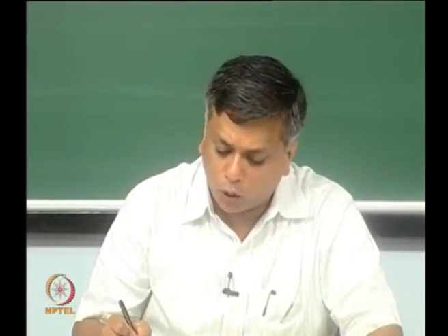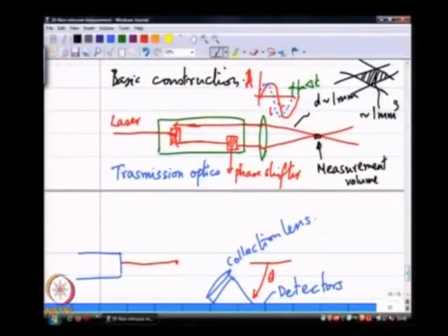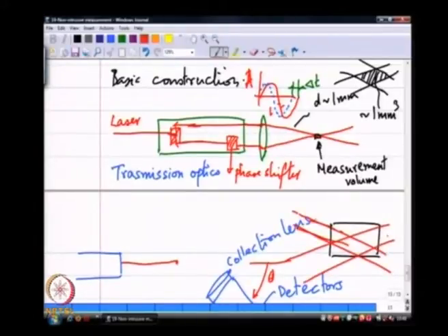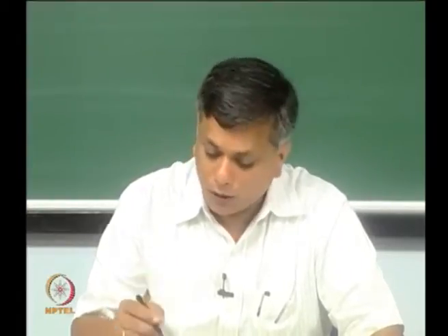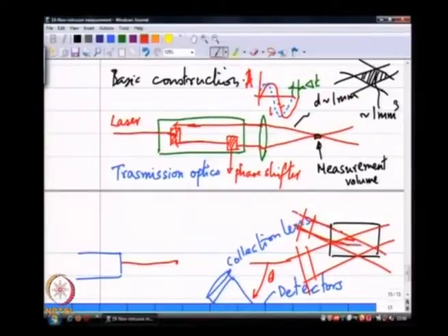Now, if I look at the measurement volume, let me first draw a zoomed out picture of it. I have 2 beams coming in, and these are in a sense plane waves that are shifted in phase slightly. There are some parts where the phases add up, where the amplitudes add, and other parts where the amplitudes are opposite in phase. So, you get essentially dark and bright bands. This is an interference pattern created due to the phase shift.